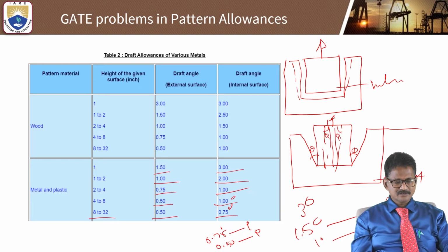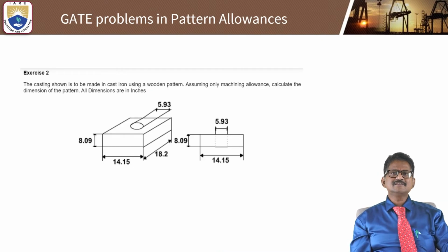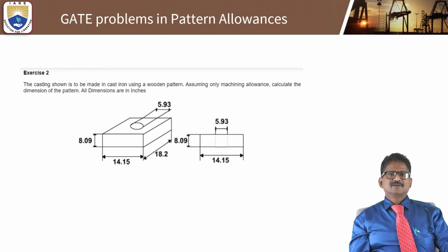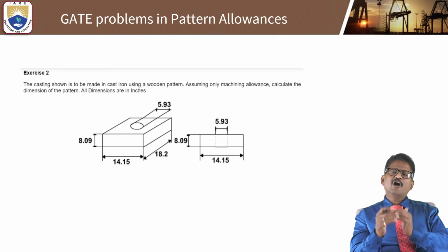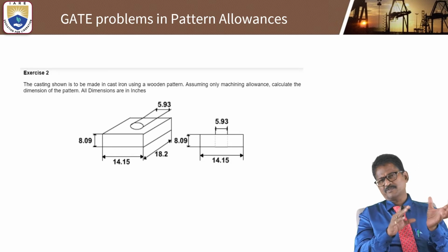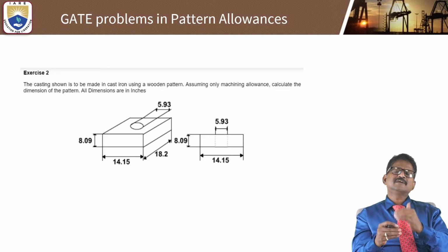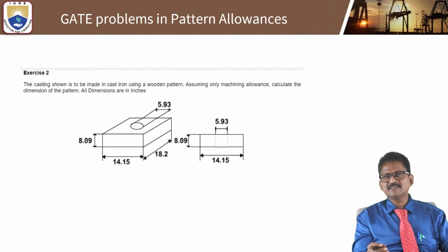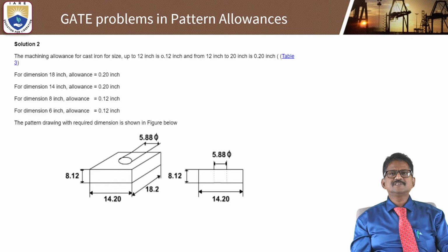Yes or no? So this is what you can provide, and even in this casting process, machining allowances. When you want to provide machining allowances, how much? Machining means after final completion of the coming out of the component, you can add some finishing. Finishing either 1 mm or 2 mm based on the material also. That is also very important.